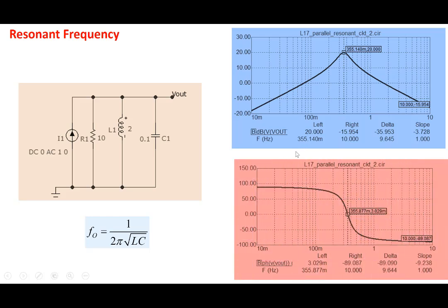Not only that, we have also been saying that at this value, the reactance due to the inductance is equal but opposite in sign to the reactance due to the capacitance, and so the two of them cancel each other. Effectively, L and C act like an open circuit, and you are left with only resistance in the circuit, and thereby the current and the voltage are in phase. So at resonance we also get zero phase.